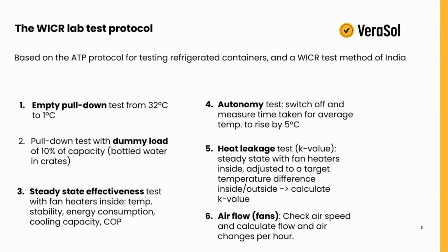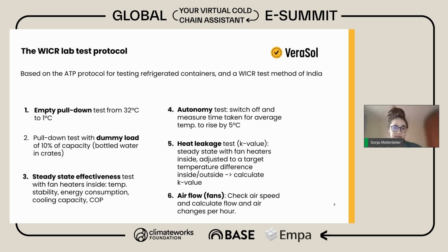The steady state effectiveness test is also in the lab test, also of course an autonomy test. We also test for the heat leakage and for the airflow. So all of those tests are there to really see how the cold room performs against its benchmarks. And then once we build more of a baseline there, they can also be compared amongst each other.